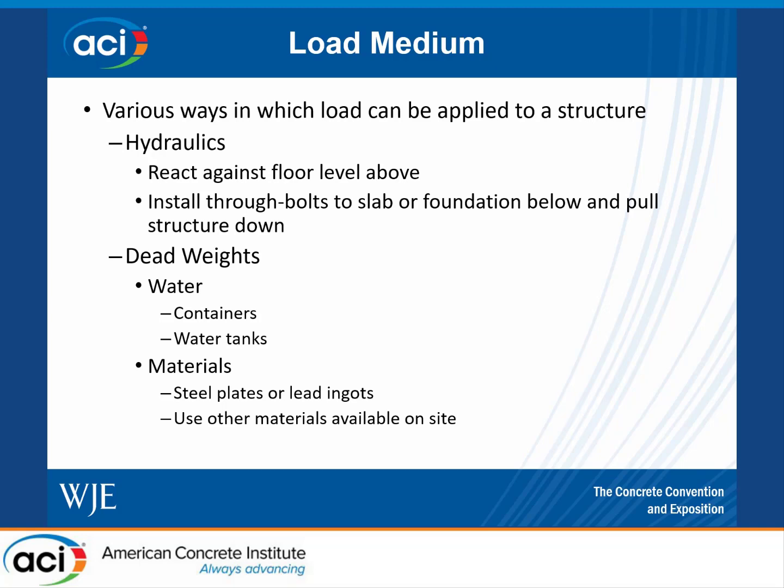To apply the load, there are various ways. The first one I'll talk about is hydraulics. You can use hydraulic rams to react against the floor level above. You can also install through bolts to the slab or foundation below and then pull the structure down. We often use dead weights in our tests as well as hydraulics, but when you're looking at dead weights, primarily we're looking at either water or other materials such as steel plates or lead ingots.